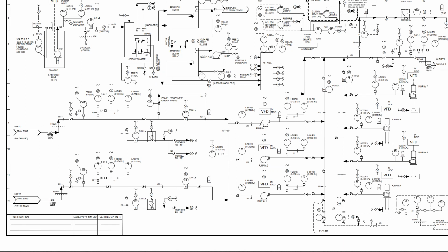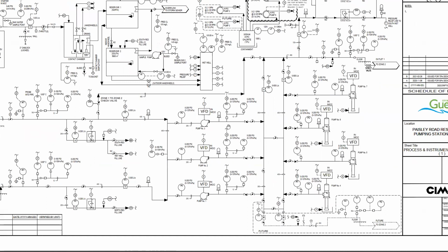We have a pressure gauge ahead of 3 of our inline horizontal pumps. So these are horizontal booster pumps. They're mounted to skids on the floor, and water comes in one side of the pump and discharges out the other side to boost pressure. One of these is running 24 hours a day. Here's a pressure transmitter on the outside of each one of the pumps.